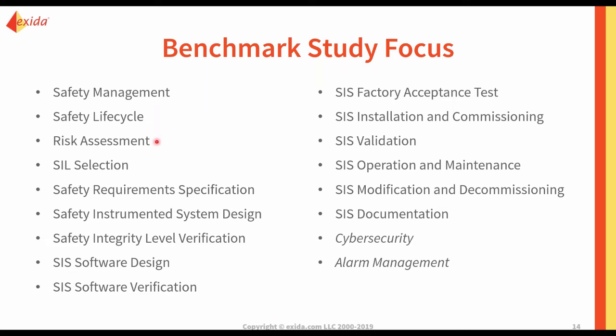So what the risk assessment procedures are, what the tolerable risk criteria are, what's done for SIL selection, whether it's layer of protection analysis or another more qualitative method, the requirements for the safety requirement specification, how the safety instrumented systems are really specified so that there's clear traceability of the requirements, the design of the SIS, going through the process for SIL verification, what's required, everything from the SIS application program design and the